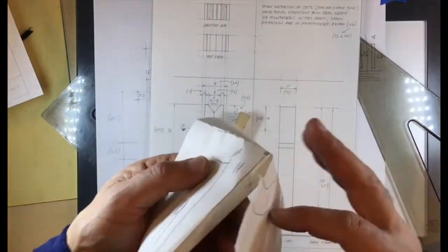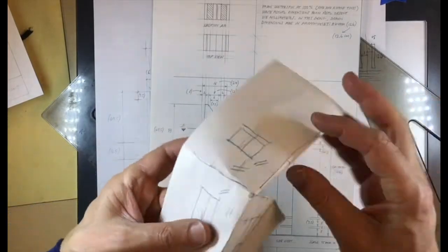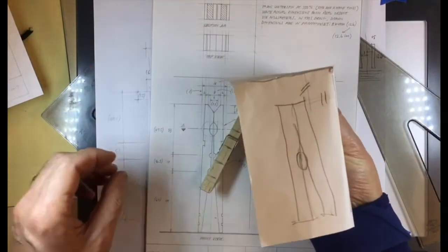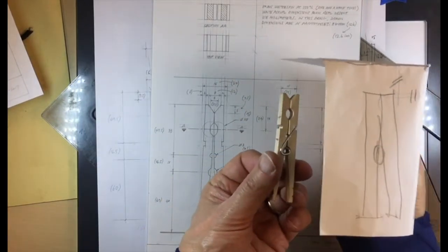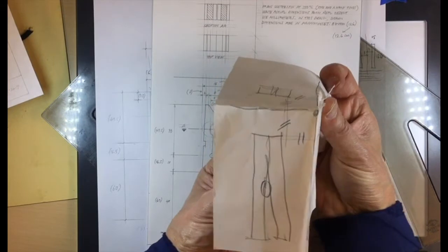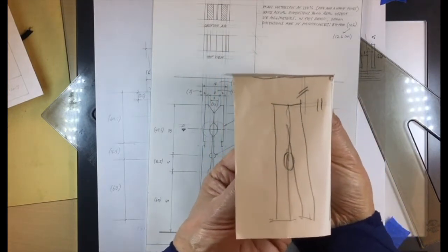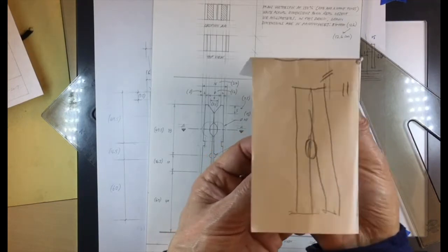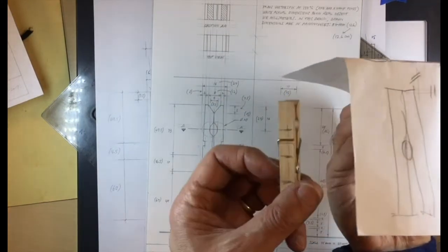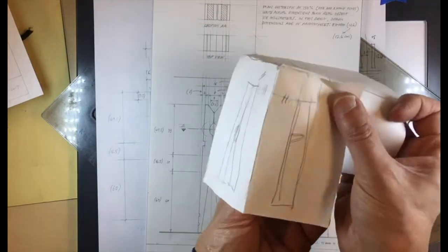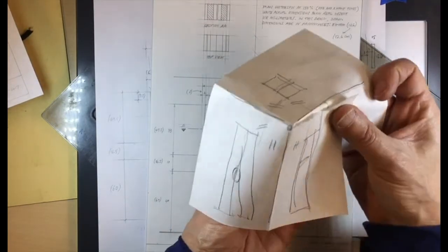What we're doing is really this. So the object is there. We're looking in, and we have this enclosure, and what we see on that glass is those views. If we project the lines perpendicular, we don't get any perspective, so we don't see any bit of the other sides, okay? So if I go around that box to the right side, I see that, and if I go on top, I see that.